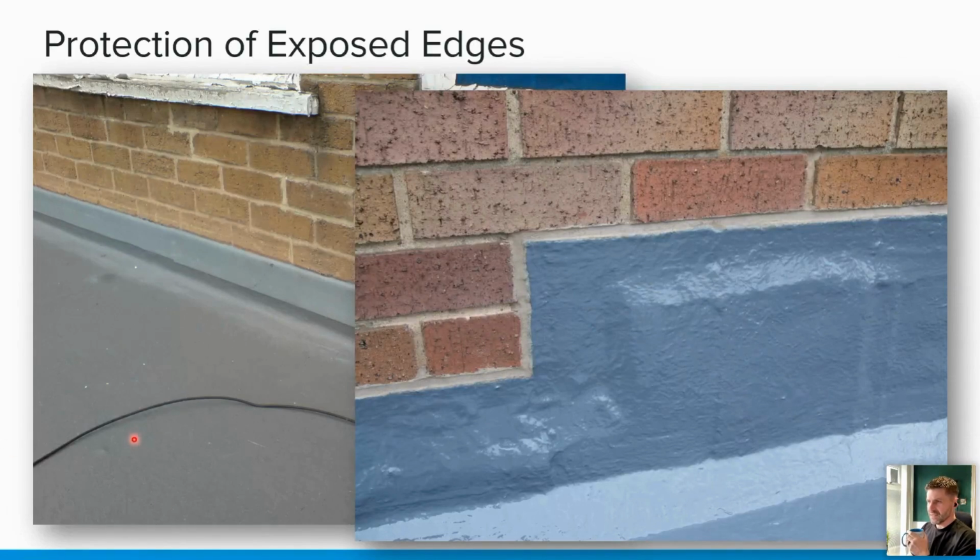In this instance, again, you've got your single ply membrane. That's what the previous one should look like. The waterproofing is taken up, taken into the chase, and then there is a flashing which protects the top of the waterproofing. So any water that's running down here is hitting this flashing and coming over the top.